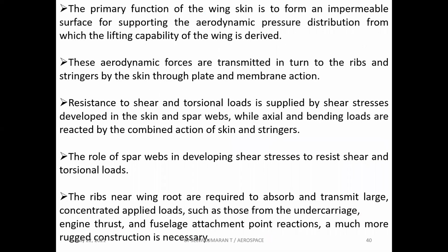The primary function of the wing skin is to form an impermeable surface for supporting the aerodynamic pressure distribution from which the lifting capability of the wing is derived. These aerodynamic forces are transmitted in turn to the ribs and stringers by the skin through plate and membrane action.